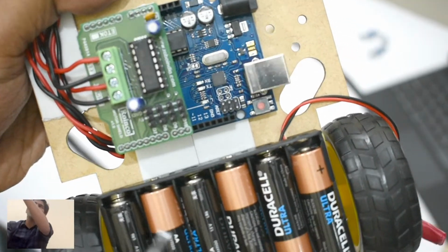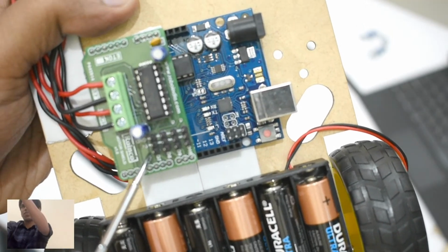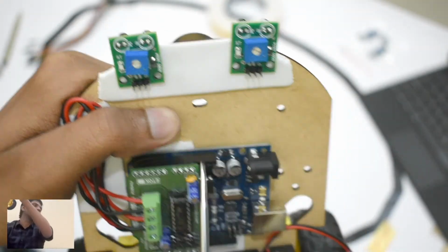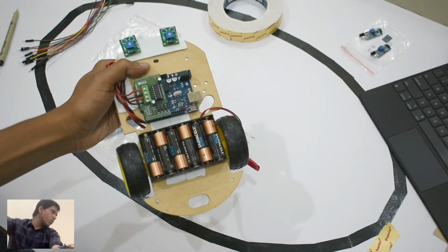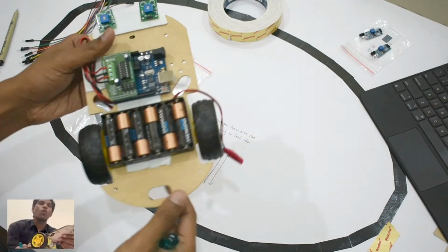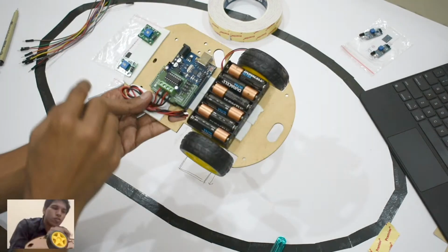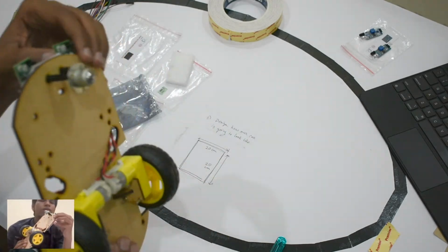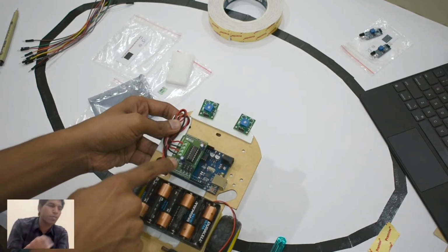Yes. So you see it's written here, D7, pin number 7 is the data pin, and this is the 5 volts pin, this is the ground pin. So all of these are written on the circuit, and the same is written on my IR sensor here. When you get these boards, once you read what's written on them, you will be able to know which pin needs to be connected to which pin. So I'm just going to connect the left sensor. This is my left sensor, this is my right sensor. I'm going to connect my left sensor data pin to pin number 7 of the Arduino.